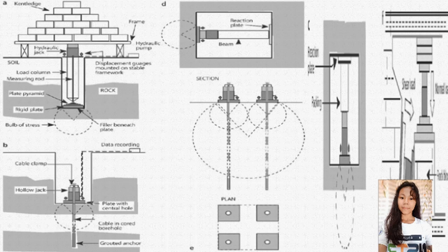The bottom of the borehole must be very carefully cleaned out to ensure that the plate bears onto undisturbed ground. Some type of filler material, generally cement, mortar, or plaster, is placed carefully at the bottom of a borehole to ensure the even transfer of load to the ground.